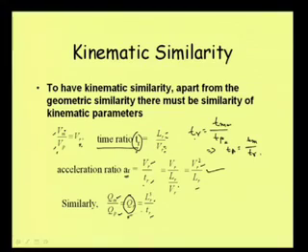If the model we are developing is a kinematic similar model, the discharge that we need to provide in the model to represent the discharge of the prototype, we can find out again utilizing this discharge ratio. So, that way we can apply the concept of kinematic similarity for deciding the discharge, time, velocity, acceleration, this relationship between the model and the prototype.